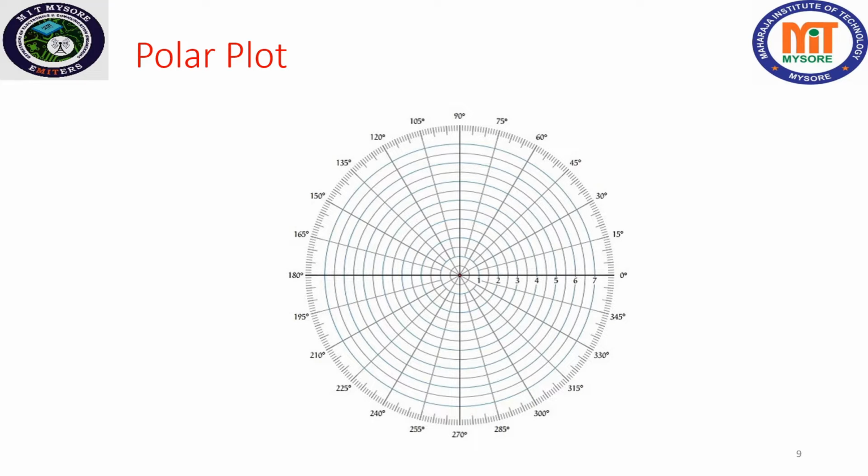Before we move to the demo part, let me say another important topic, which is about the polar plot. This is the plot which we use to plot the radiation pattern and then determine the half power beam width and use it for calculating gain and directivity. So this is the plot where we can draw our radiation pattern like this, for example. Then if this is our 0 dB, minus 3 dB line like this, we draw the intersection points and then measure this angle, which is theta E for the electric field.